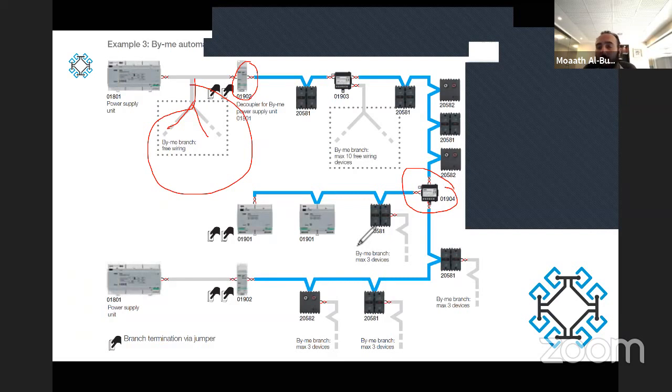Okay, I have a question about the power supply. Sayyid Anas, we don't need two power supplies. We have to calculate how many milliamperes the devices draw from the system and decide on that which power supply and how many power supplies we need. This power supply, I said earlier, will use 1280 milliamp.